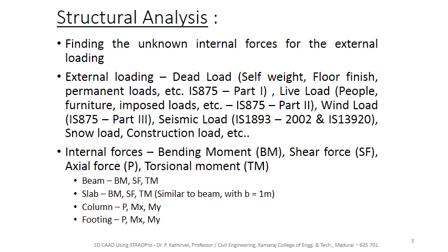Generally the types of internal forces are bending moment, shear force, axial force, and torsional moment. Beams are flexural members which are subjected to bending moment, shear force, and torsional moments. Slabs are similar to beams, which are also subjected to bending, shear, and torsion if any, where the breadth of the member is taken as 1 meter for design. And then columns are vertical members subjected to mainly axial compression, in addition to moment along X and Y if any. And footings are also designed for axial compression along with moment along X and Y if any.